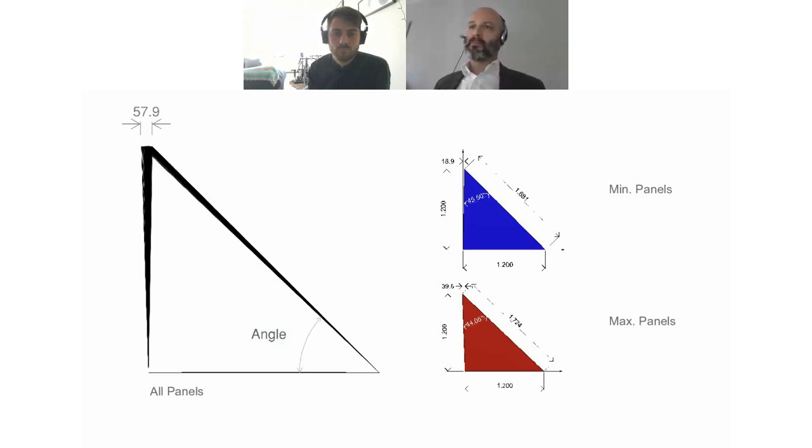Whilst the cladding system was an open jointed rain screen, so could accommodate some geometrical tolerance, having a joint which could be over 60 millimeters was not really an option. Also, the client wasn't keen on having a puzzle of over 1,600 individual panels. So, not wanting to completely unpick the design, we decided to adopt a different approach.